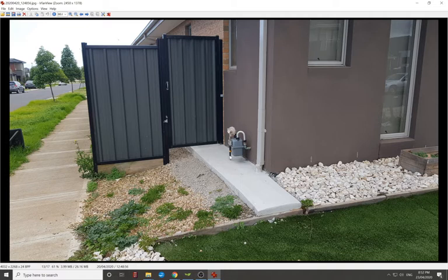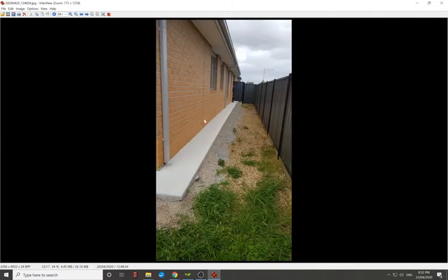Houses, yeah, it's not very good the way it's working at the moment, and it's not clear as to whether you really truly have to do this. Like I was saying before, you definitely have to make sure the water runs away. I mean, you could just run dirt and cover. I can understand covering the top of the slab with dirt running away from the building. That's definitely a must, and it's usually done in the site clean or final site clean.